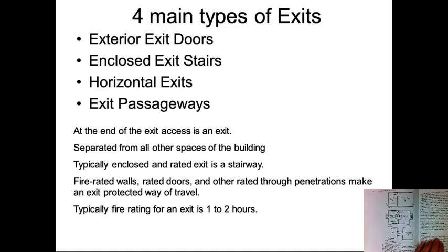Fire-rated walls, rated doors, and other rated penetrations may make an exit a protected way of travel. Typically, a fire rating for an exit is 1 to 2 hours. So if you go through this, it would be an exit, even though these are the stairs and we don't get outside until we get to the bottom of the stairs. But this is your exit.